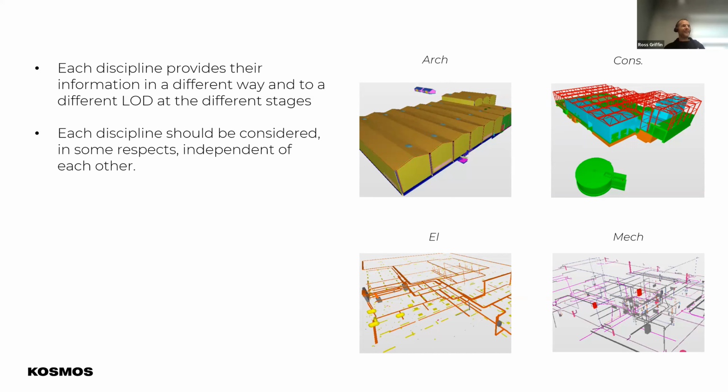It's diagrammatic, it's specification, it's almost like functional requirements rather than actual design within a model or AutoCAD, purely because obviously the architecture hasn't been locked down and the structure isn't there yet. So you will have different disciplines supplying information at different LODs and LOIs along the project lifecycle. It's not uniform for each of the design stages.